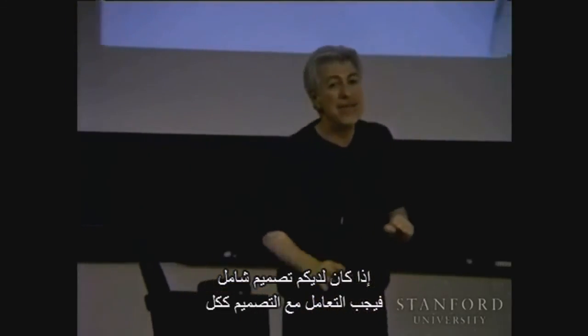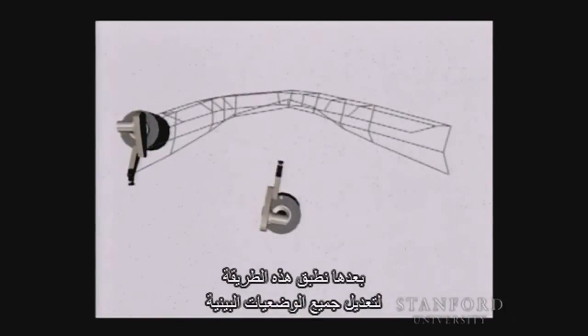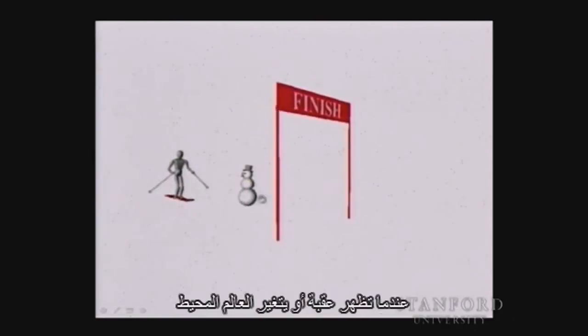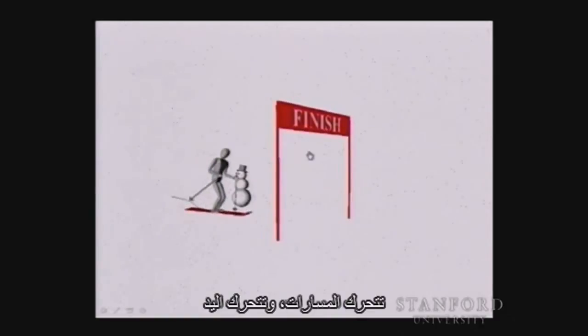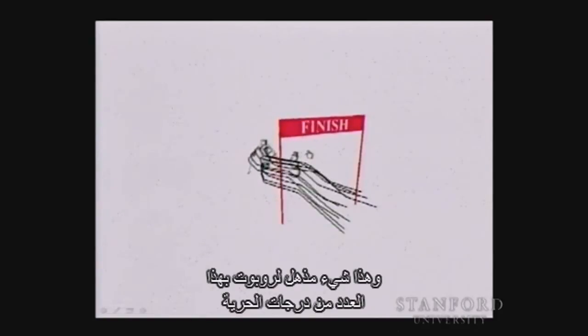But if you have a global plan, you need to deal with the full plan so that you will not reach a local minima, and we then apply this technique to modify all the intermediate configurations so that a robot like this would be moving to a goal position through this plan. When an obstacle appears or the world is changed, the trajectory is moving, the hand is moving, and all of this is happening in real time, which is amazing for a robot with that number of degrees of freedom.